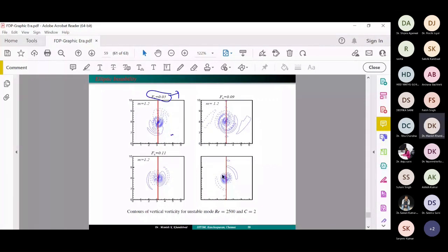So a purely elliptic nature, and that nature is one of the dangerous instabilities in fluid mechanics, which is observed in the Stewartson vortices. And it's calculated by me that we have obtained the elliptic type of instability in the flow fields. So that is a very interesting way of seeing how it changes slowly as stratification is increased. I observe how it is going to be changed. The vortices are going to be changed in such a way, and finally we convert to the elliptic instability.